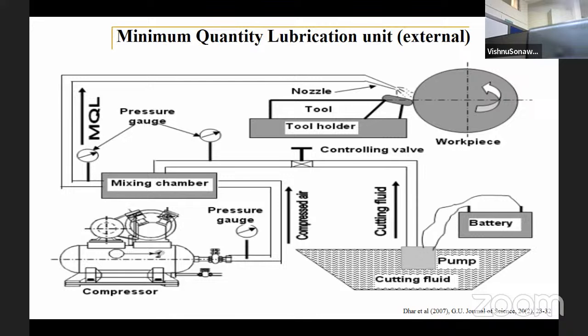You know very well, coarse grain size filters and fine grain size filters are used, and the air will be lubricated, and the pressure of the air will be regulated through the proper FRL unit or filter regulator, and air at 6 to 8 bar pressure will be supplied from this end.